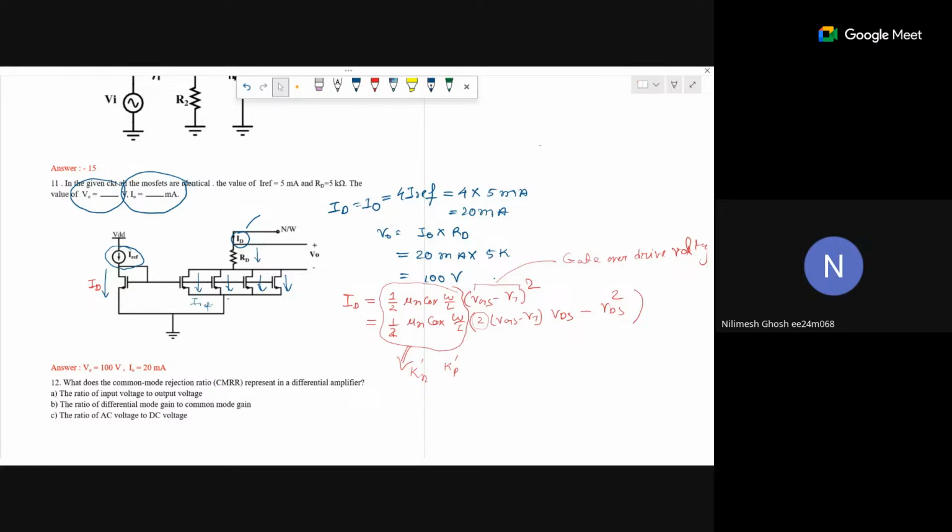Okay. Now see both of these equations. The thing I want to point out is that both of the equations depend on this W by L ratio. Now for a technology, this L is fixed because L is taken as L min. Let's say the technology node became 2 nanometer, 3 nanometer. It doesn't mean that this L min is 2 nanometer, 3 nanometer. It depends upon the process by which the MOSFET is made.